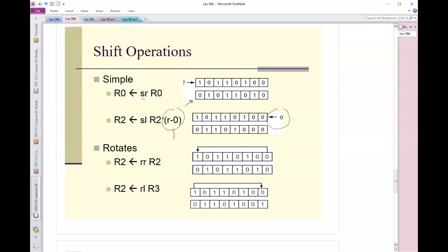One of the classic functions out there is a rotate. When I do a shift, I actually lose a bit. And so with the rotate, like this is a rotate right, everything gets shifted in the right direction. That LSB comes around and becomes the MSB for rotate. So we have a rotate left, rotate right. It's really quite interesting. RISC-V doesn't have rotate instructions. They have shift instructions, and I'd say most microcontrollers, most instruction sets do contain rotate instructions.